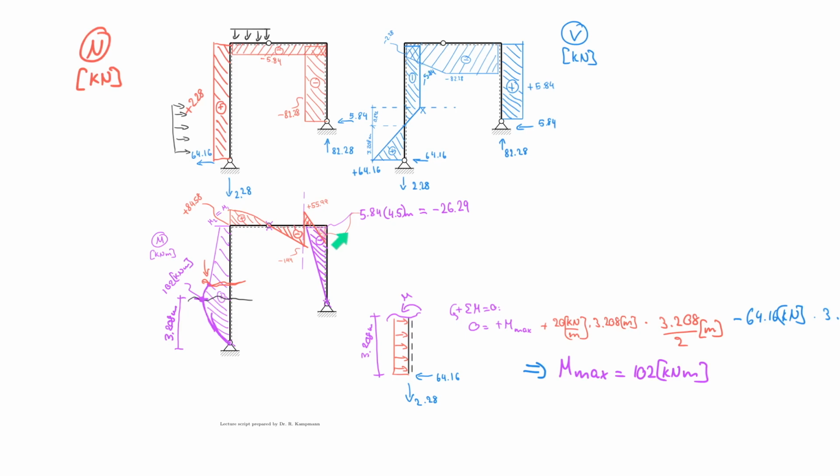Similarly, the moment diagram down here relates to the shear force diagram, just like we learned before, where the shear force is the derivative of the moment or vice versa. Just be careful when you follow your integration logic, right? Because you could also say that your moment is the integrated shear force. Be very careful when you go down that route, because you don't want to forget about the integration constant here, which is the concentrated moment at that location.